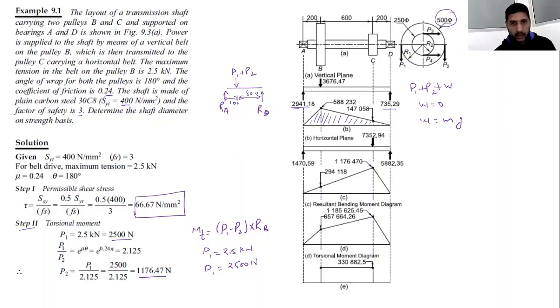ठीक है ना. अब आपको सिर्फ reaction forces निकालनी है. Reaction forces कैसे निकालनी है ये आपको हम बता देते हैं कि देखिए vertical force क्या आ रहा है आपका, that is P1 plus P2 और upward force क्या लग रहा है RA plus RD. इसको आप equation number 1 बोल दीजिए. ये वैल्यू आपके पास है already. अब taking moment about any point, जैसे आप A के about moment लोगे तो एक equation बनेगा, that is taking moment.